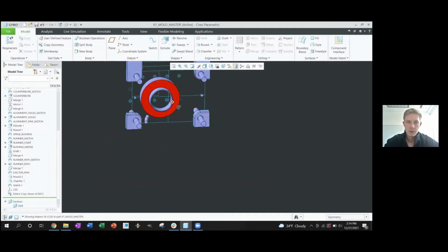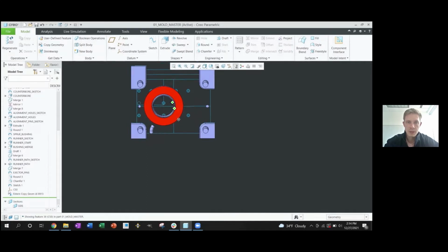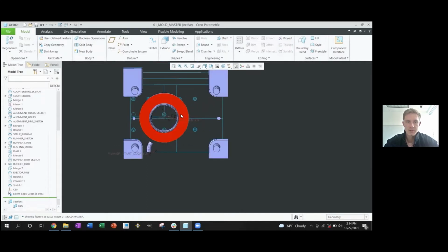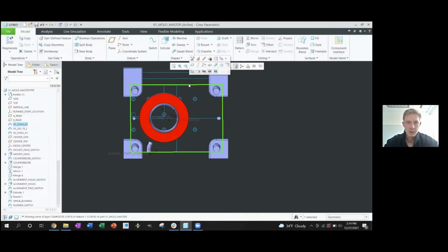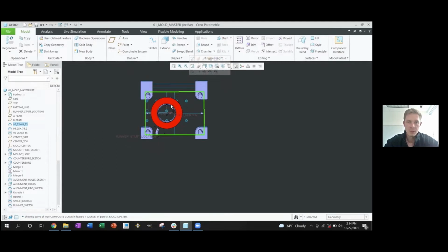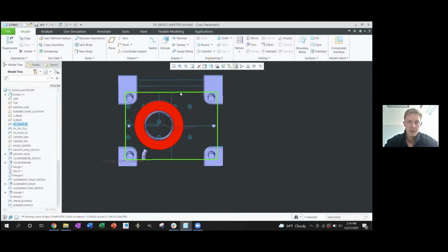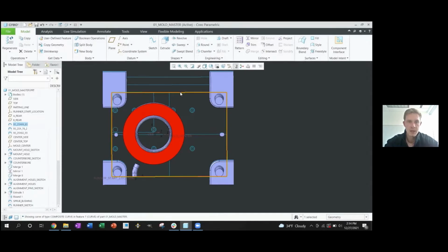One thing I want to touch on before we get any further with this mold design is the mold block size that we're going to be using for this part itself. What we're looking for is a 10mm wall offset between the part and the block itself. The smallest pocket size in this master model is going to allow us to achieve that.